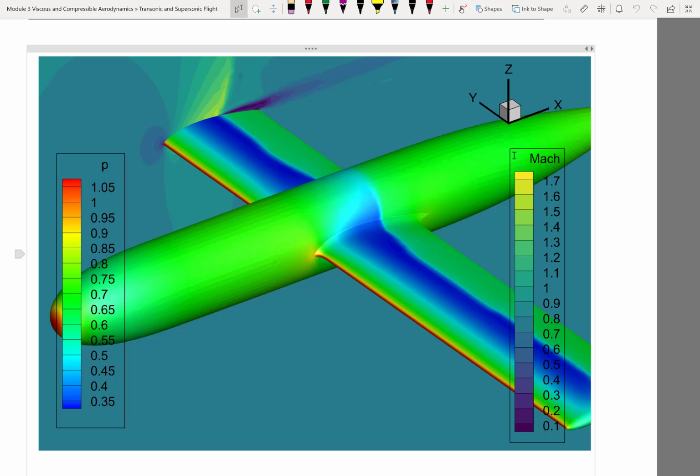In supersonic flows, the streamlines are qualitatively the same. They also shrink and expand, but the velocity in the expanding portion behaves completely differently. Instead of the velocity reaching a peak at the minimum stream tube, the velocity keeps increasing and the pressure keeps decreasing after the stream tube reaches the minimum area.